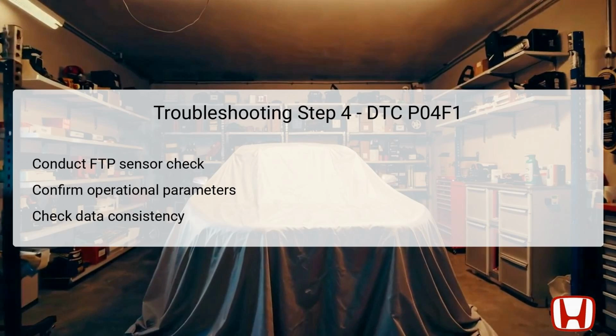The FTP sensor is crucial as it helps the PCM monitor vapor levels in the system, and a failure in this sensor could contribute significantly to the emergence of the P04F1 code. Hence, accurate testing is vital in isolating faults.